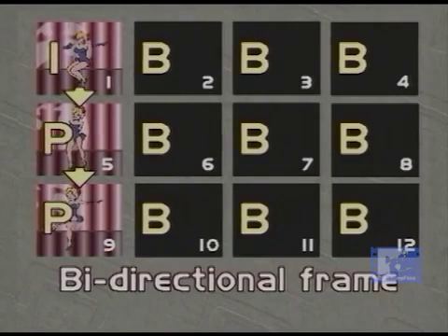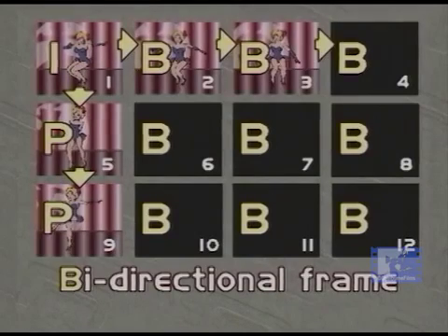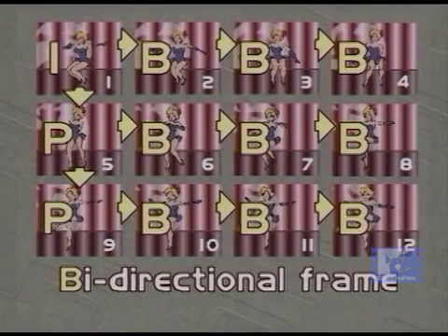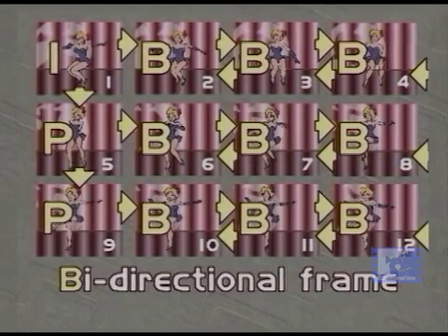B-frames are bidirectional frames that are coded using motion-compensated prediction from the nearest preceding I or P frame and the nearest following I or P frame. The sum of the bits assigned to the I, P, and B frames cannot exceed the allocated transmission speed in any given second. Not all MPEG-2 systems use B-frames. Those systems which do employ B-frames achieve a more efficient level of compression by up to 15 to 20%. Less data, therefore, is needed to achieve the same video quality. Decoders using B-frames, however, must have a second frame buffer. This adds to the cost of the total system.